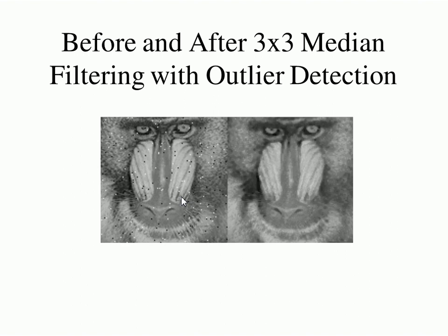So what you can do is you can look underneath where the median filter is, see if there is any shot noise there using the outlier detector, and then apply the median filter only if the shot noise is present. It can be a big win. So if there's occasional shot noise, it's really good to know that you don't need the median filter at certain points. So knowing when to apply the median filter, as opposed to making an interactive tool, making an automatic tool for applying the median filter, that just sounds so important and good, right?